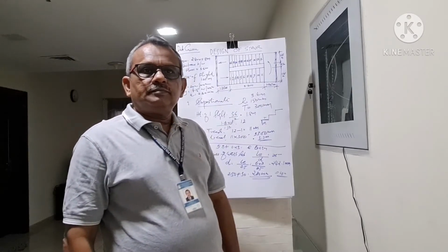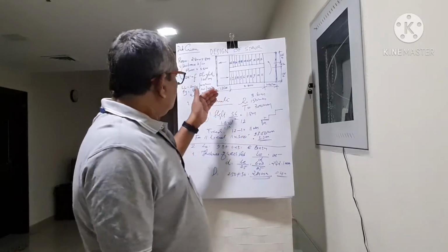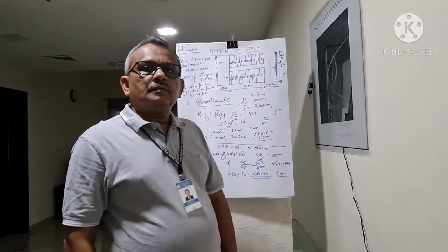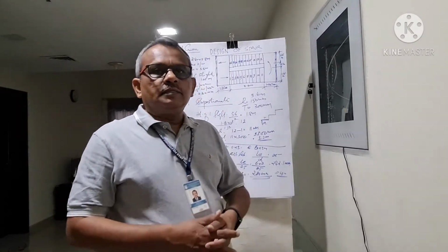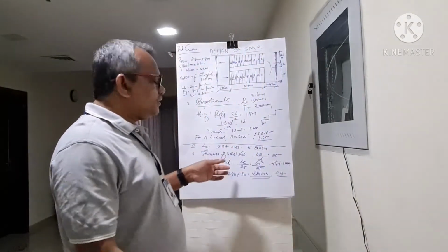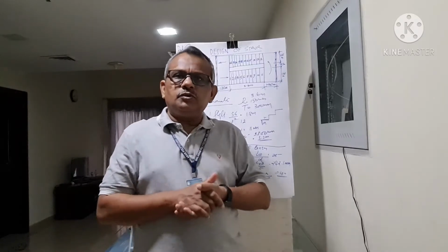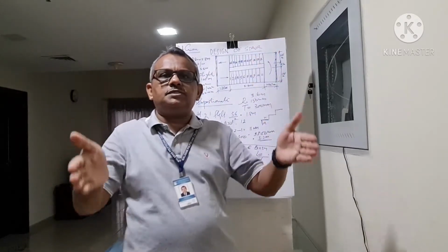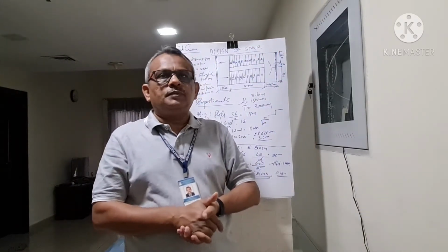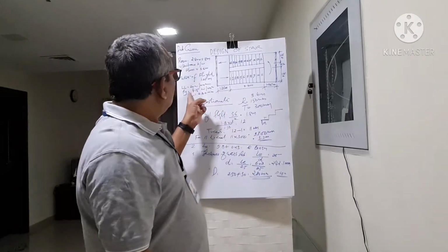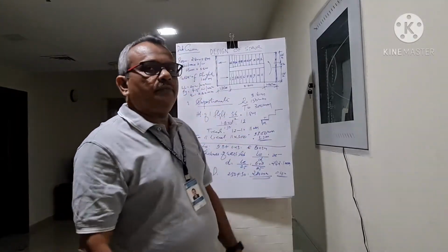Is it okay? Now, the next step. After proportioning the steps or the stair, the second step is to find out the effective span. As in the case of beam and slab, the effective span is the center to center distance between the supports. Here the thickness of support or thickness of wall is given as 230 mm.